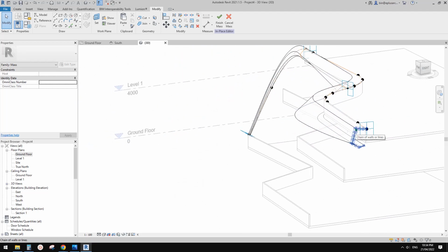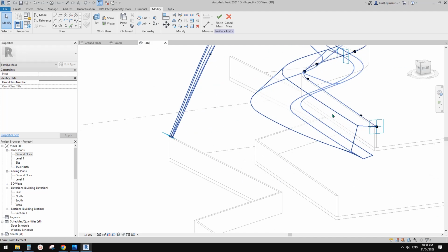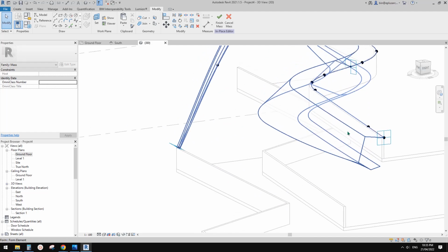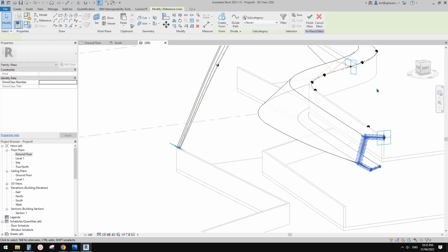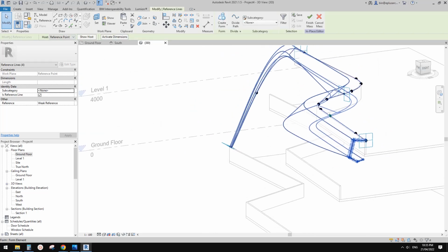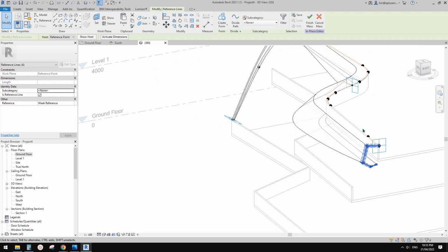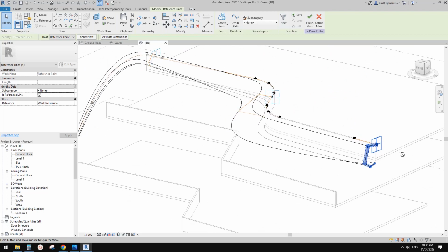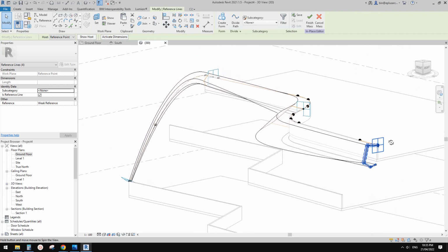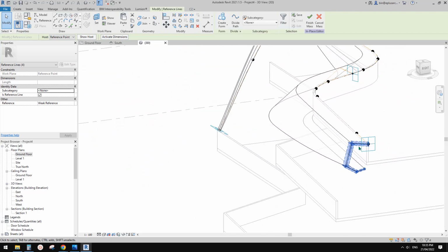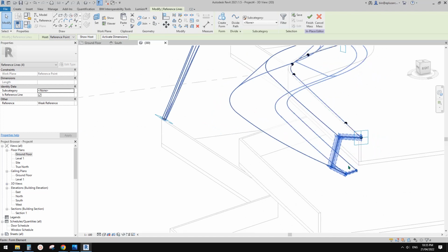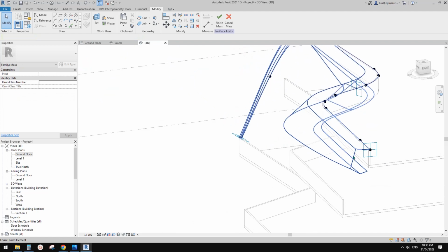It's easier to try to create the form first, because sometimes when you have different shapes, I think Revit will have issues creating a form. So sometimes you just try to create a simpler, basic form first, and then try to adjust the profiles. So, and yeah, that's it.